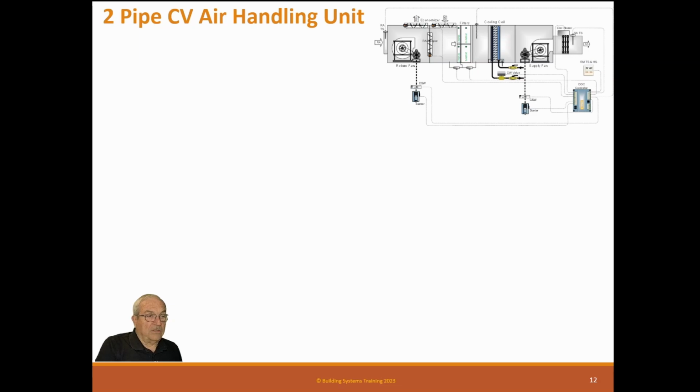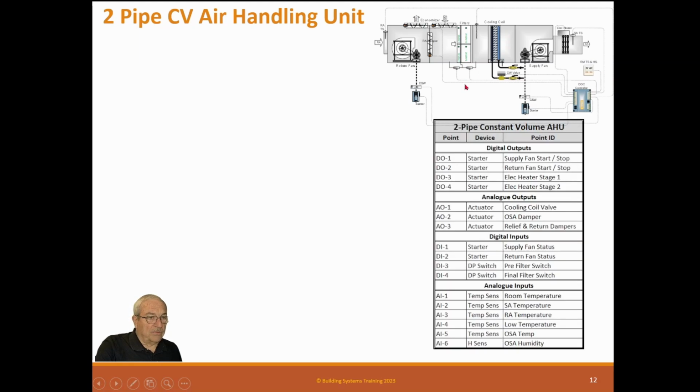Now the other thing too is that we're not in VAV, but when you get to VAV, they don't work at all. Because as the airflow goes down, the pressure goes away, because it's not a direct proportional relationship. So you can't use them on VAV. You can put them there, but they don't mean anything. So I've only shown the filter switches here so you can see what they look like, how they work, but really we don't use them very often.